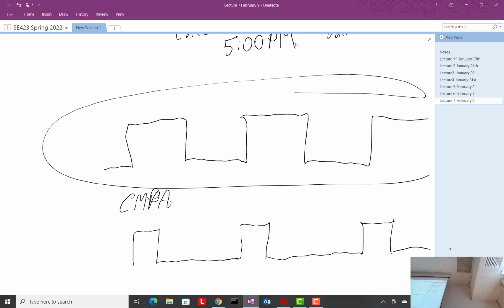That wouldn't make sense at all. So 25% of that 5 seconds, we'd be telling the motor to go in the positive direction. Because of the time constant of the motor, the motor would get up to speed, wouldn't it? Be going at some fast speed. And then 75% of the time telling it to go in the other direction, it's going to go back to that negative direction, isn't it? And that's a terrible control. That's awful. It's spinning really fast and then spinning negative really fast.